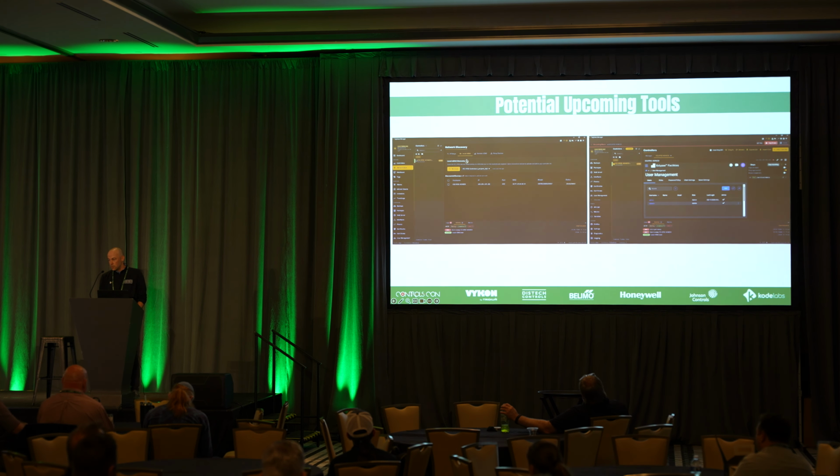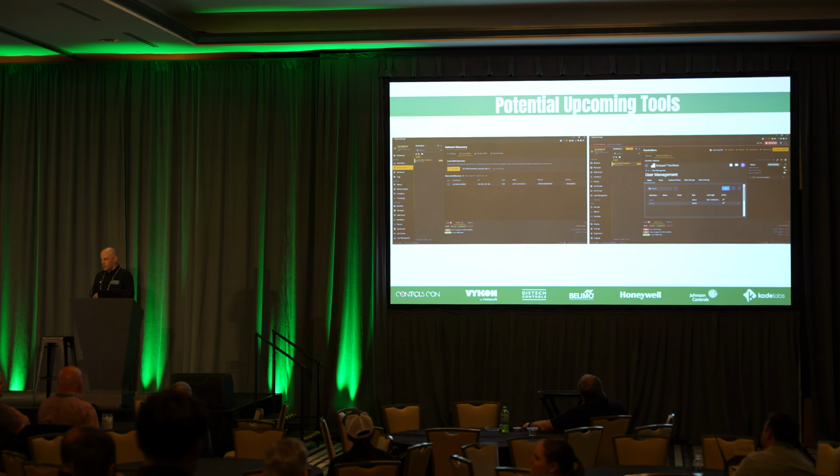Local mDNS is the same way that we network scan in Express Network Utility, but it will scan for all of the controllers on that network, and you can manage them from here. Or we can do a remote mDNS scan, get to a controller, and then scan all of the controllers underneath that on a separate subnet. So we're working within the constraints of the IT world at this point, but we're able to get to devices and do some functionality underneath that we would not be able to do without our controllers in place. Another thing that's very unique and interesting to this tool is he put macros in.